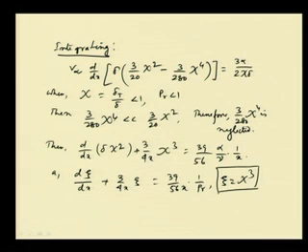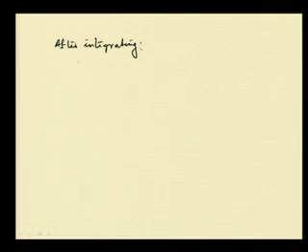Now, we can do the integration. This integration has to be done with the help of an integrating factor, and if we do the integration, after integrating, we get that zeta is equal to 13 by 14 into 1 by Prandtl plus c into x to the power minus 3 by 4.